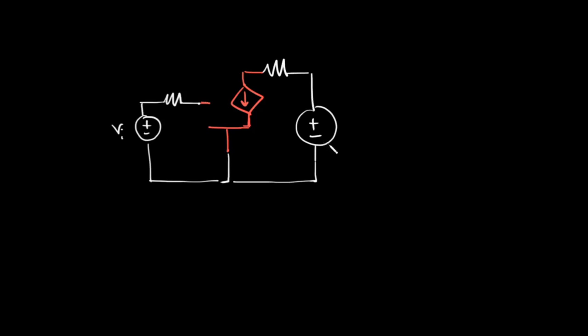Okay, so let's try to do some of the analysis that we did using BJT for the FET. We will put in some values. Suppose, exactly like the BJT, I put here 1K and here 2K, and my supply will be 20 volt. I will change the input, putting different values at the input, and for this FET I will choose gm equals 2. Let's see what values we get.